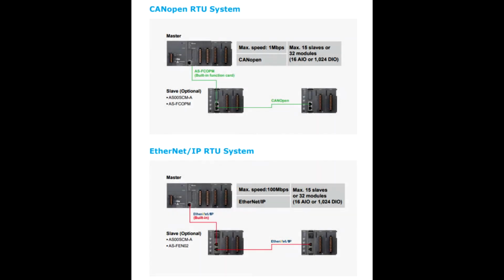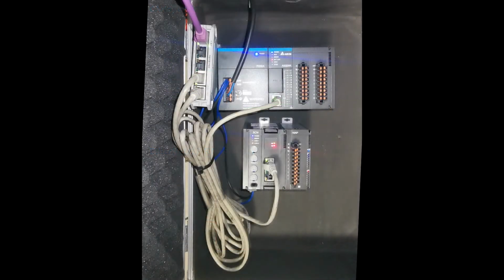VFDs. The AS0102 communication module can either be connected directly to the PLC in a linear topology or be connected to the PLC through an Ethernet switch, which allows a star topology network. There are no settings or termination resistors on the AS0102 communication card. Once plugged in, it is ready to be configured. In this example, we will connect the PLC, RTU module and computer through an industrial Ethernet switch.